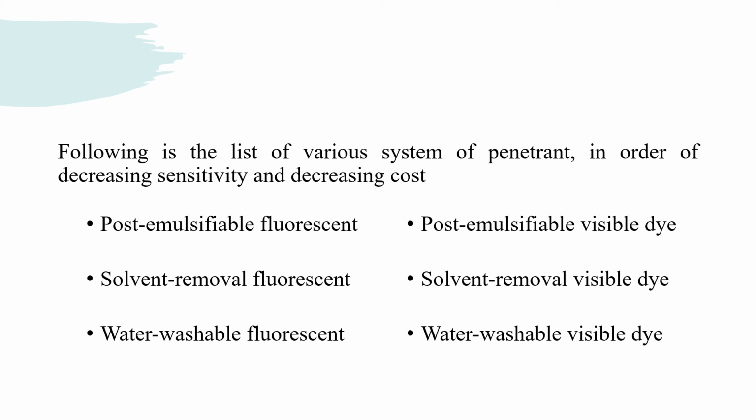The following is a list of various types of penetrant in order of decreasing sensitivity and decreasing cost. First one is post-emulsifiable fluorescent. Then solvent removal fluorescent.